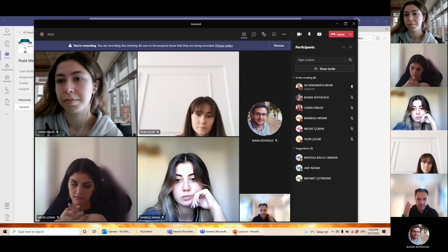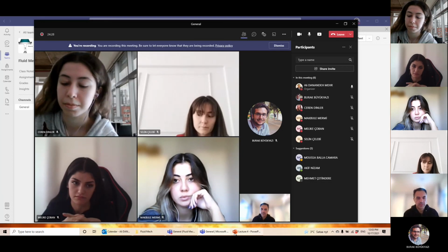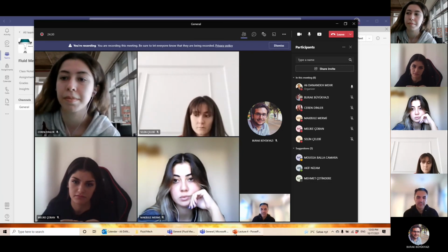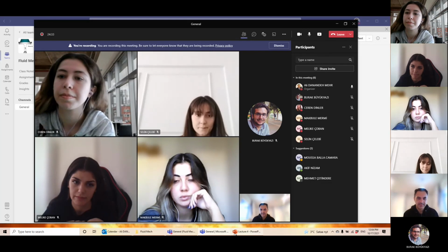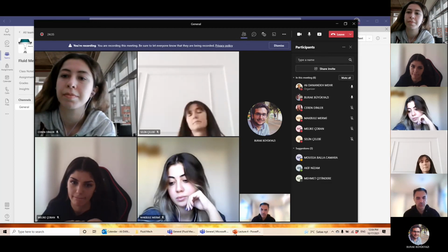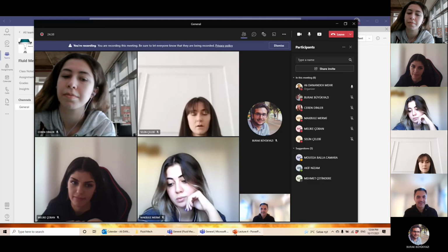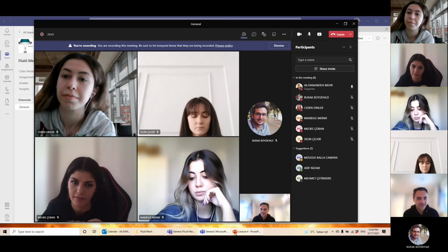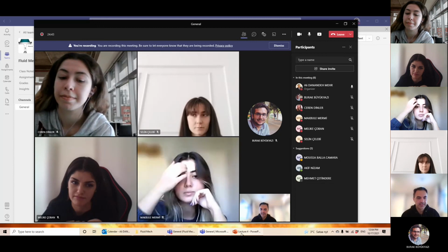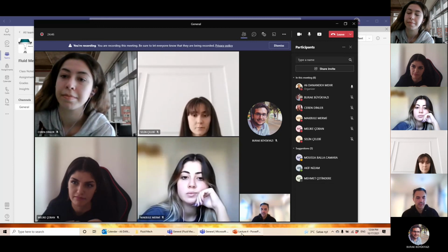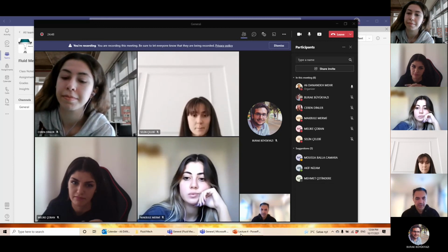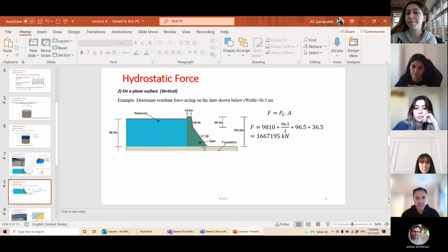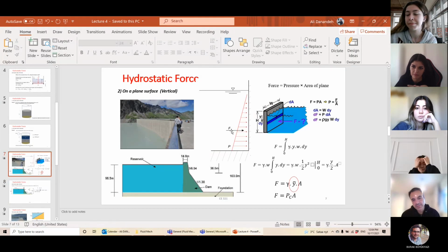You are right. In the vertical, do you think it should be the centroid? Because we found pressure at the centroid. No idea. You are allowed to say nothing, because actually it is neither middle nor centroid. The location of the value of this F can be found with the location of the centroid, but it acts on the pressure center.